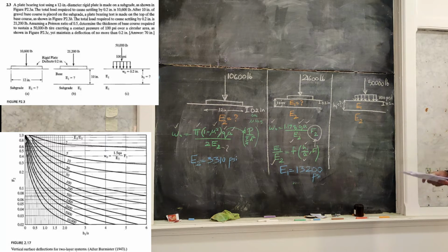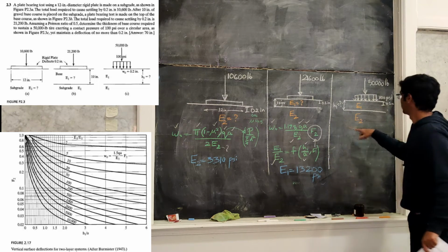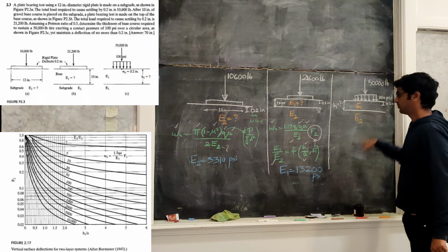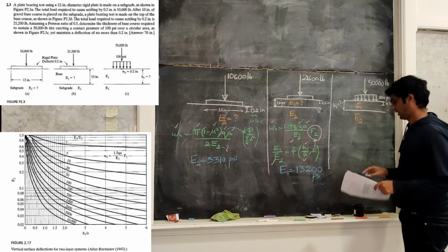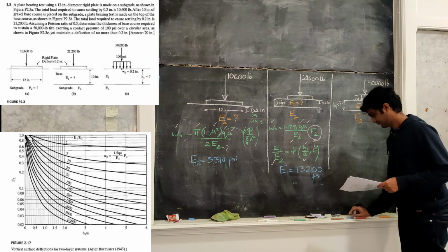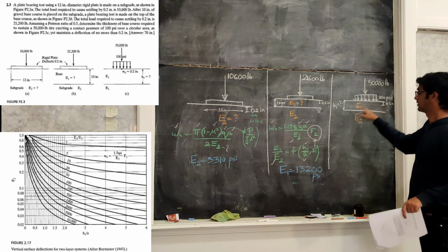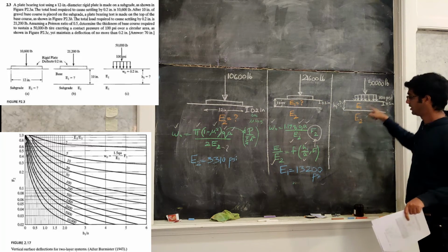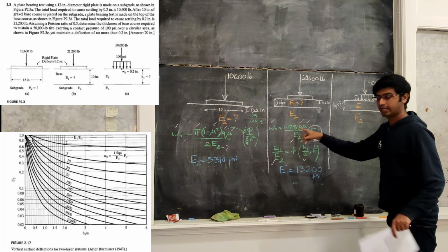Okay. The last one, the third scenario. Now, again, it's a 2-layer system. Base E1, subgrade E2, which is already known. E1, E2, you already know. Now we need to find the thickness H1. How do you do this? Now the difference is it's the same equation, but instead of a rigid plate, it's a flexible tire. So the coefficient alone will change from 1.178 to 1.5.